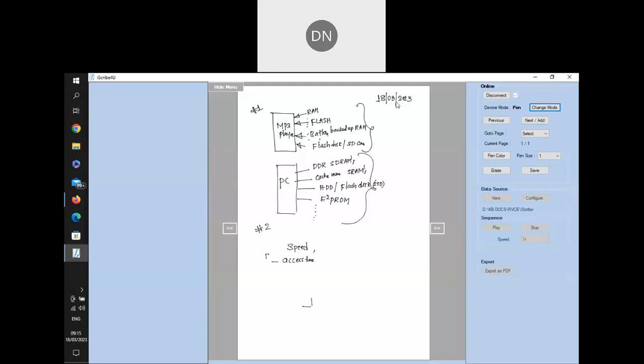If somebody asks, what is an access time? I say 3 clock cycles. So what is a clock cycle? Clock cycle is nothing but 1 over the frequency, or the speed at which the processor runs. If it's 1 megahertz, it's 1 microsecond. If 3 clock cycles are required, I can just say that 3 microseconds is the time required for placing the data from the address location onto the data bus. So 3 microseconds is my access time.